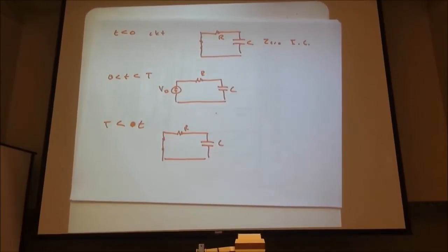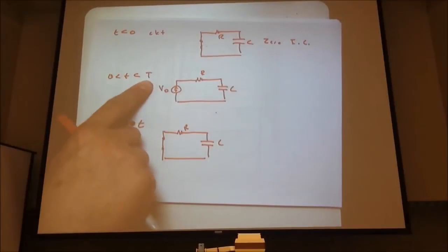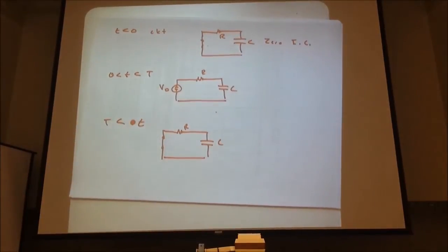A long time corresponds to, as you just said, the capacitor being fully charged, having the full voltage. Well, we don't know that's the case until we know what capital T is. And we had that kind of loose description. We said a long time being 5 time constants. And so if T was larger than 5 time constants, yeah, that would be a long time. But if it's less, then no, it's not fully charged.